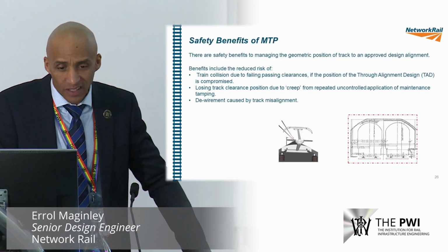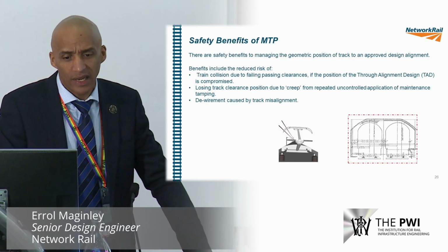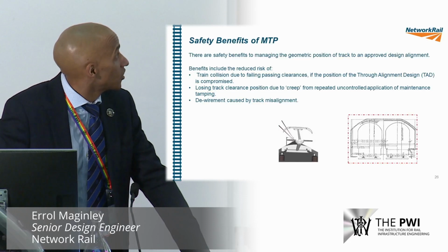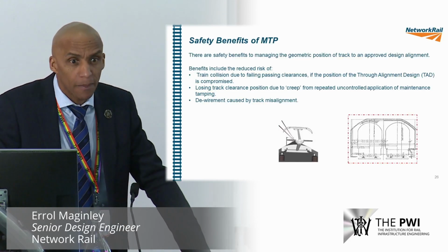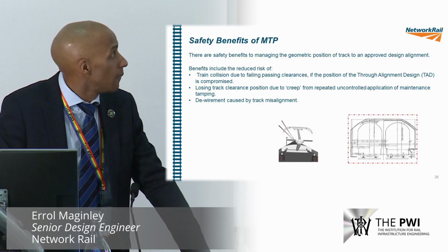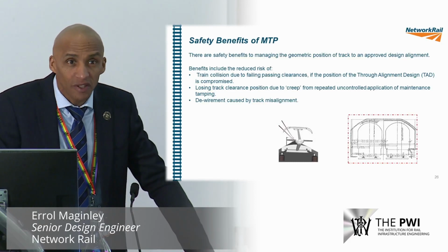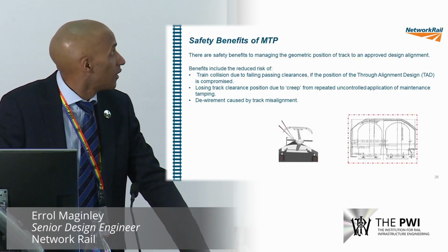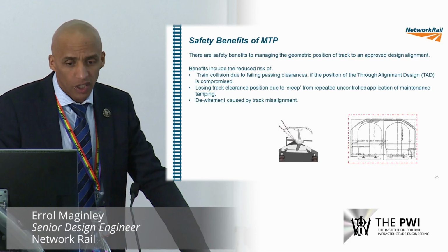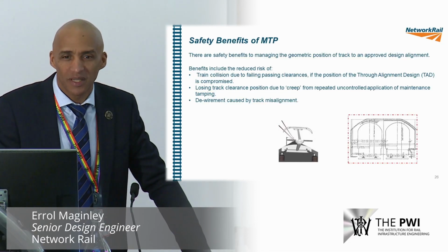Well, what are the benefits? Well, there are safety benefits, of course. Reduced risk of train collision due to failing passing clearances, or losing track position from creep. This is where we repeatedly maintain the track to an uncontrolled position, and over time we can actually lose the design position of the track. And of course, to reduce the risk of dewirement caused by track misalignment.